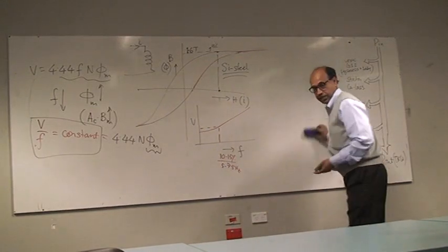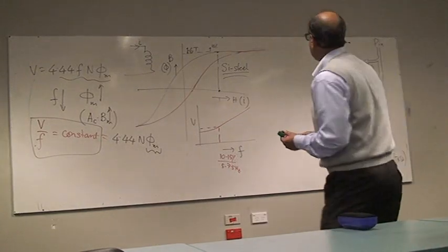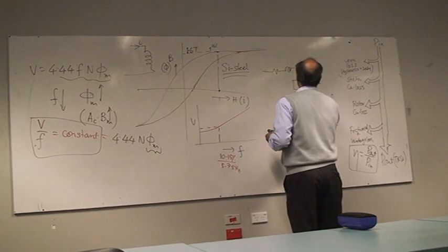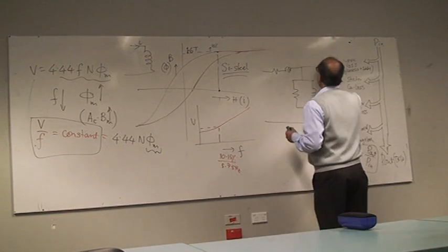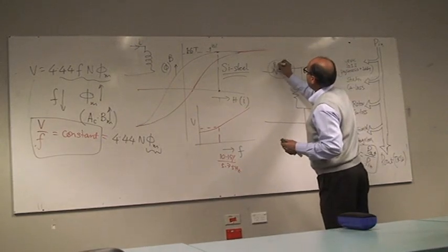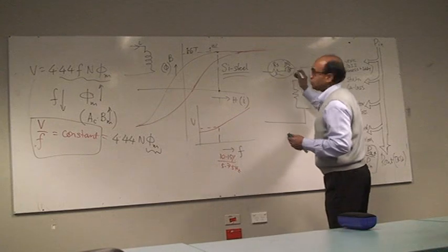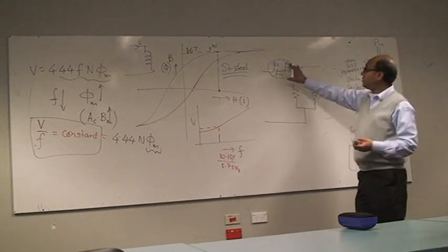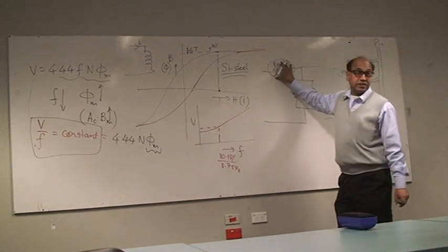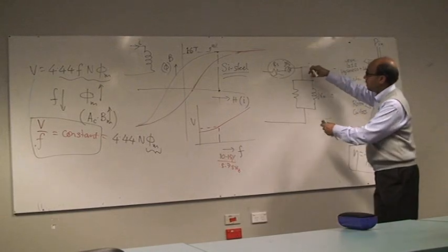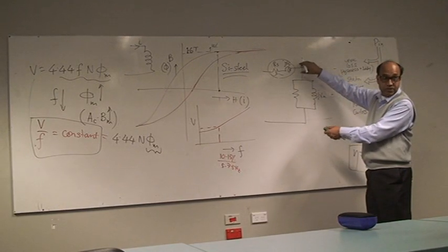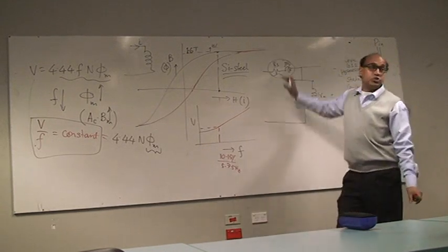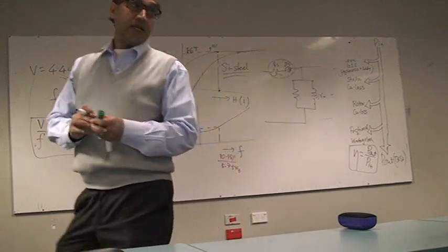So basically, if you think of that situation, this part, your RS and jXS, they actually drop some voltage. Then only you are creating the flux. So that voltage drop needs to be compensated. Even though you may say, is it increasing more flux? It's actually not increasing more flux, because your flux is created by this part of the voltage. So just to overcome this drop, you have to increase the voltage slightly.